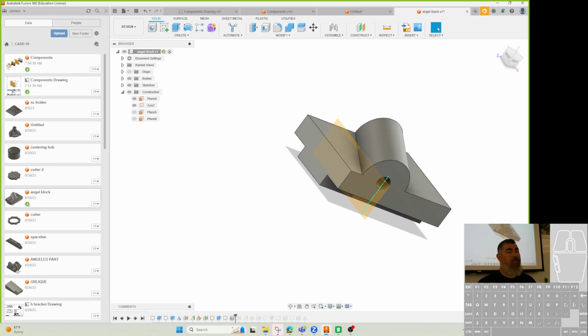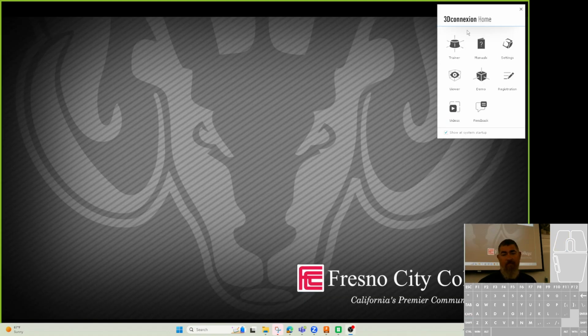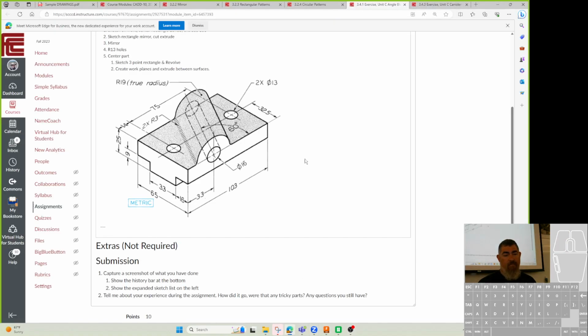Yep. A little bit. In the real world, if you were given a drawing like this and you were going to manufacture the part, let's say you were as green as you could possibly be in the industry, and you drew that circular bump there at the top, just on the face, that's obviously not going to work, because that's not the true radius. Is there a check and balance of any sort? If you just drew a regular arc here and then tried to do a loft, or drew a line here and swept it, it'd be skinnier. It wouldn't be the right shape. You'd be able to tell. Yeah, the bosses would know right away.